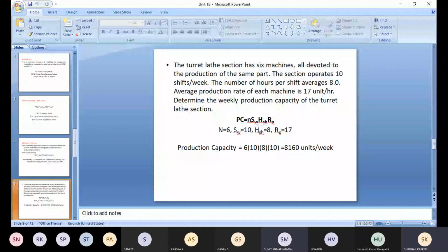But please remember, the work handling time and work fixing time will be different for different machines. Definitely the non-operation time will be increased. To avoid this, on a single lathe one can do plane turning as well as threading, so that we can do combined operations. If you do combined operations, the number of workstations can be reduced and the floor space will be reduced.